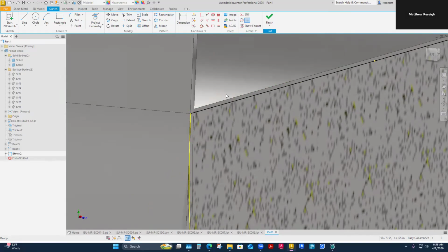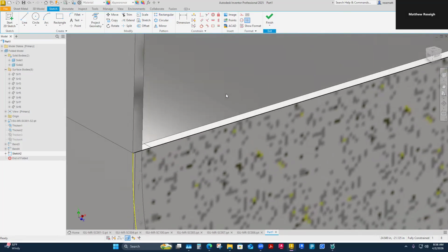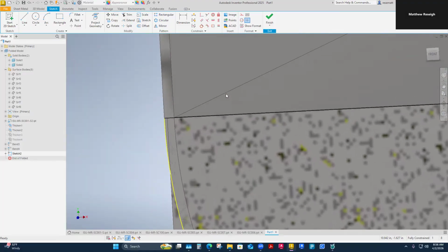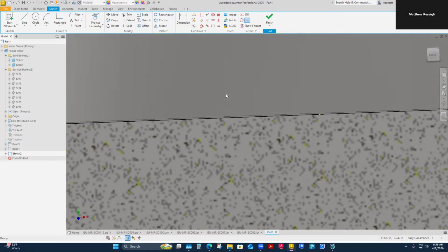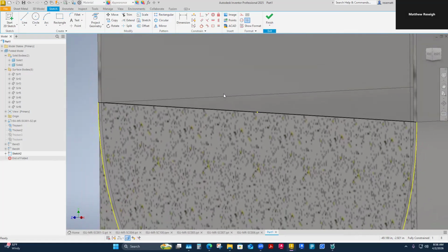So just be aware that, especially in some sketch positions, you might have to overextend the profile that you want to cut beyond the point of the material. Every once in a while, when you do cuts across bends like this, you can get some fragments of the part still remaining, and that can sometimes throw off a flat pattern, not let it flatten out. I don't think I had that issue here. I was able to just project that single semicircle and then connect the tops, and that's going to be sufficient to remove the material here. But just watch yourself every once in a while. Sometimes you have to offset that a little bit more to make sure you cut it through clean.